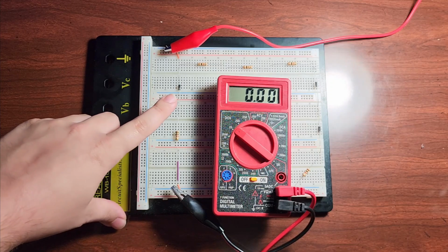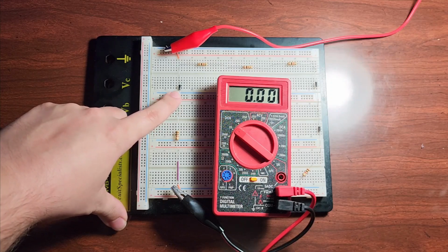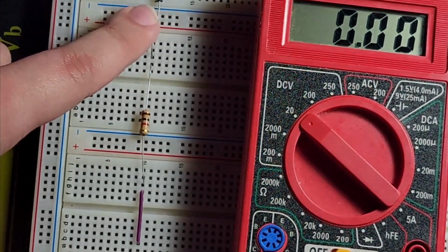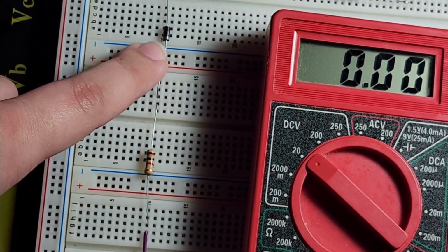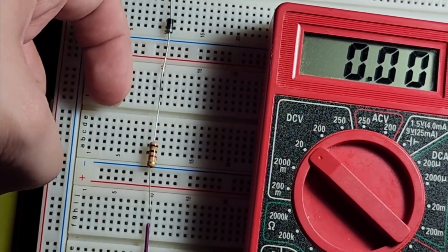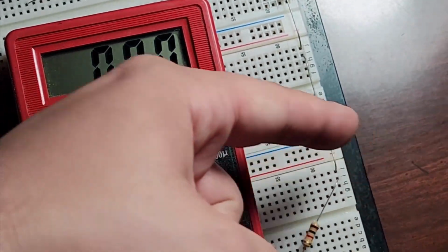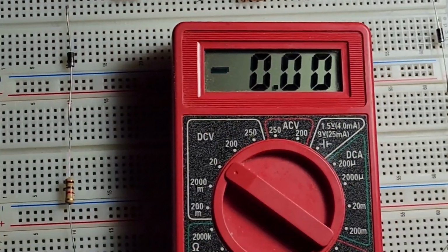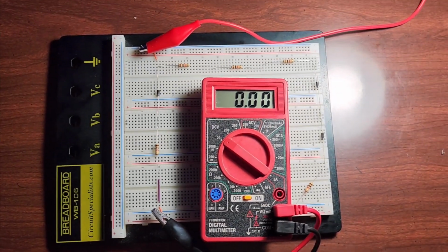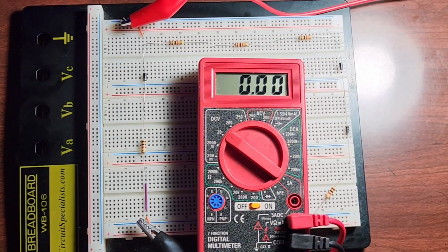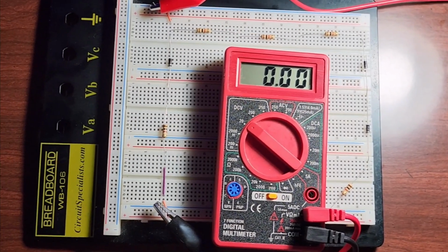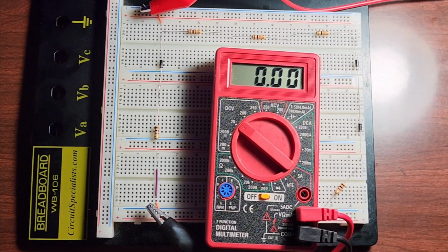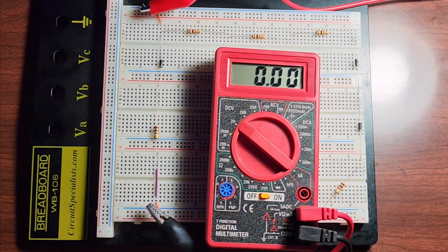We have our diode facing down. So if you can see this little, let me zoom in real quick here, right there. You see the little lines are going to be pointing down in the diode direction. We also have the same thing over here and up here, right there. And each resistor is going to be a 1K resistor. And these are your typical diodes we use in class in the lab. I believe 1N4006. Let me check. I believe they are, yeah. 1N4006. So they have a 0.7 voltage drop across them.